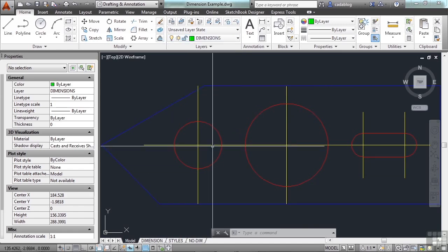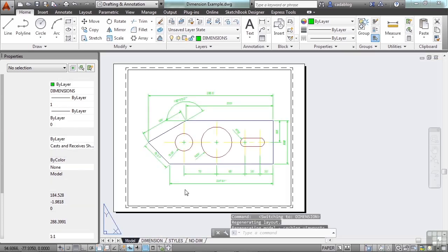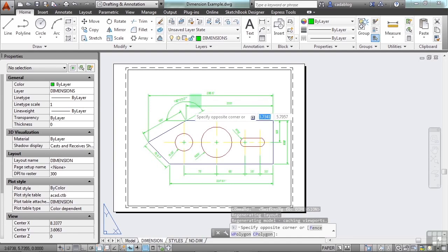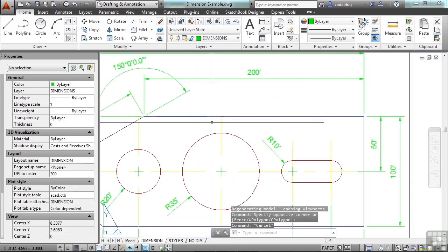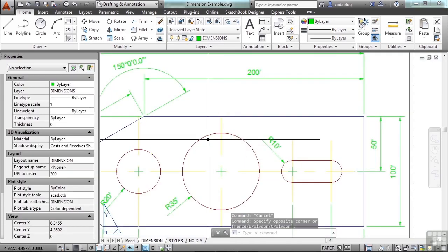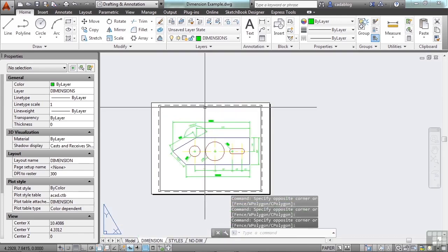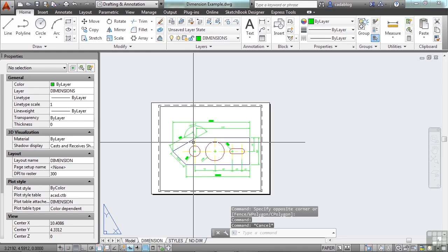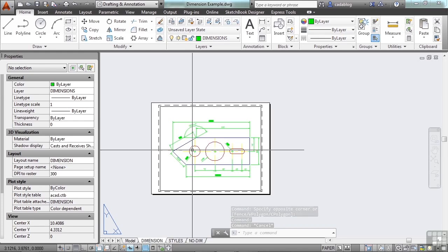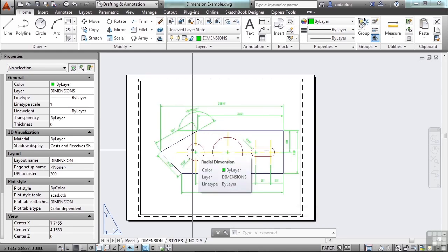That's it. Now let's go to paper space, and you can pick any of these tabs. The only thing here are our dimensions. I can't pick any of the line work because they're in a viewport, so there's no line work here. This is a very simple example, but it's very clear. And sometimes the lines between model space and paper space can become blurred, and it's okay.